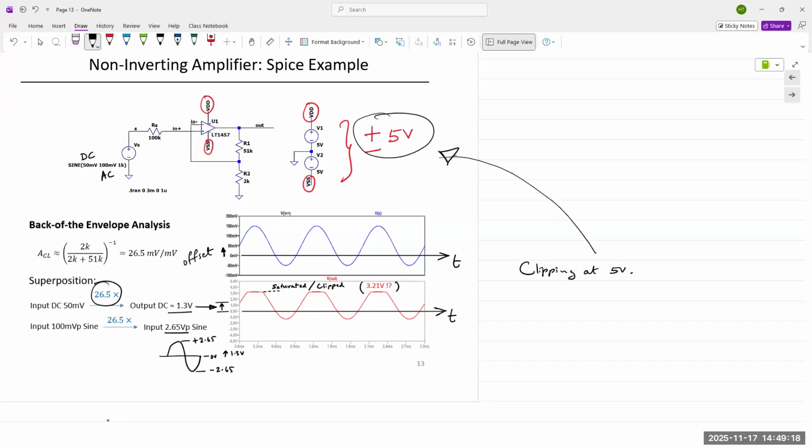But the op amp does not run by itself. The op amp has several transistors and resistors and other components inside it, so some energy is consumed by the op amp itself to run the system. The output is restricted to whatever is left over. In this case, it is just a shade over 3.2.